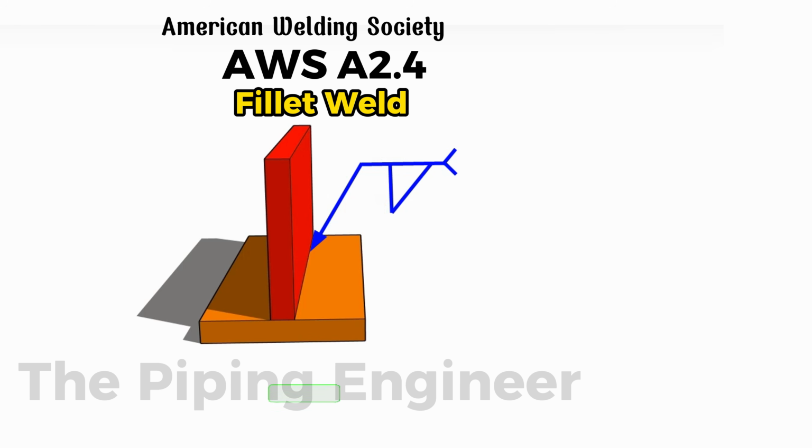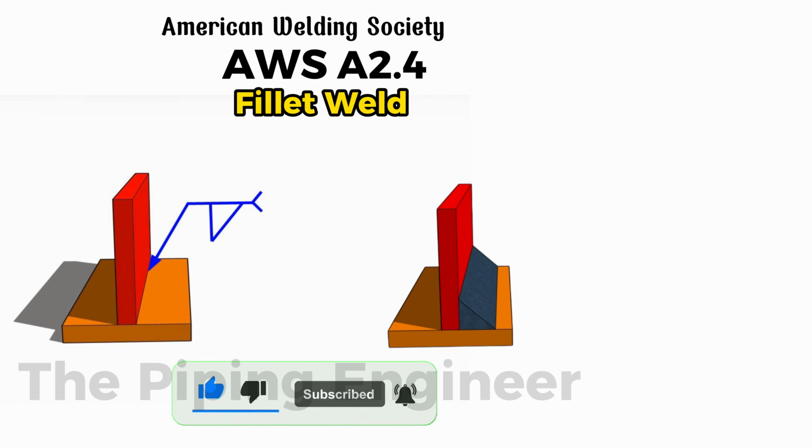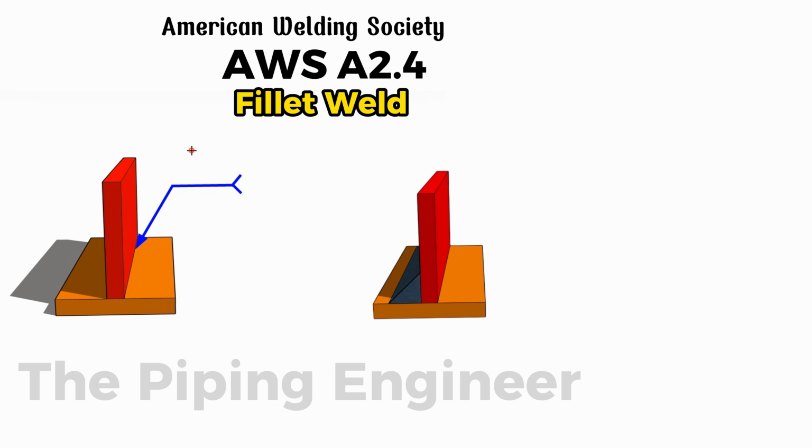On an engineering drawing, a fillet weld is represented by a small right triangle symbol placed on the reference line. If the triangle is positioned on the bottom side of the reference line, it indicates that the fillet weld must be applied directly on the arrow side, the side of the joint to which the leader line points. If the triangle is positioned on the top side of the reference line, it means the fillet weld must be applied on the other side, the opposite side of the joint away from the arrow.